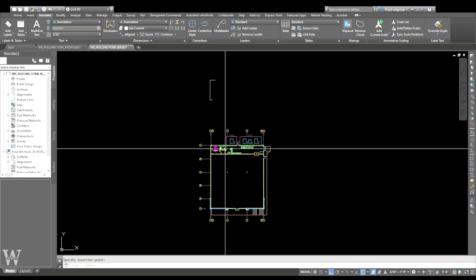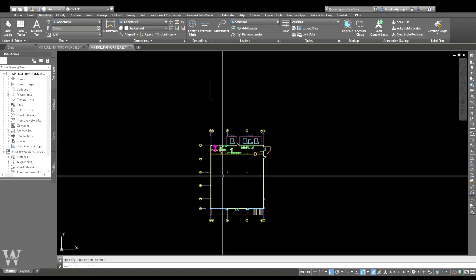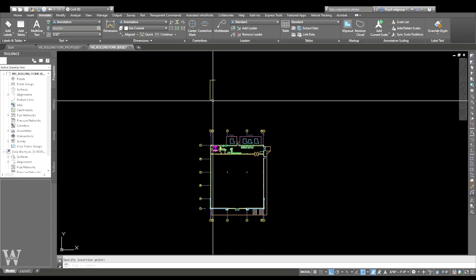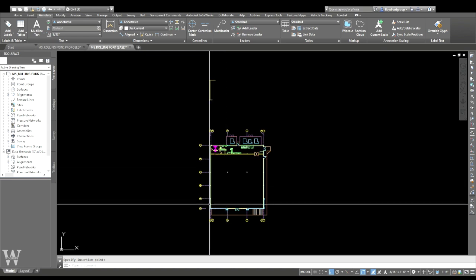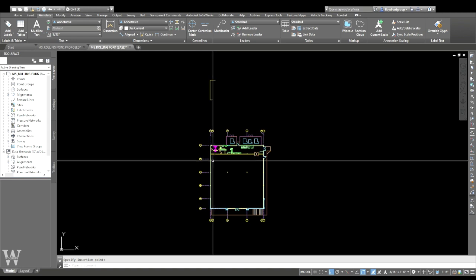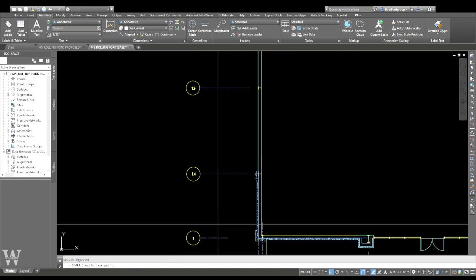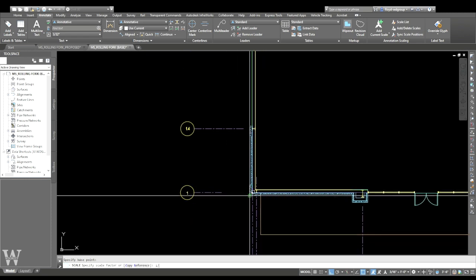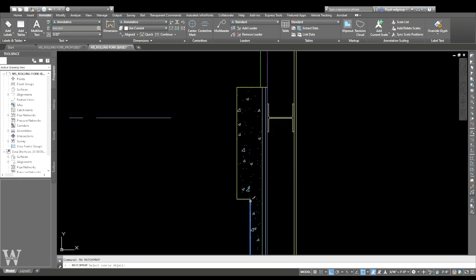What happens is there's settings in here that when you insert objects, whether that be when you copy and paste objects in, they either come in as your units as 1 or units as 12. And I never know which one. I don't know where the setting's buried at. I just know this. When I bring in something and it's way bigger than it should be, it's 12 times too big. And if I bring it in and it's way littler than it should be, it's 12 times too small. So I can just grab that object, pick that base point and scale it down 1 divided by 12, and I got it back where it needs to be in the right place.